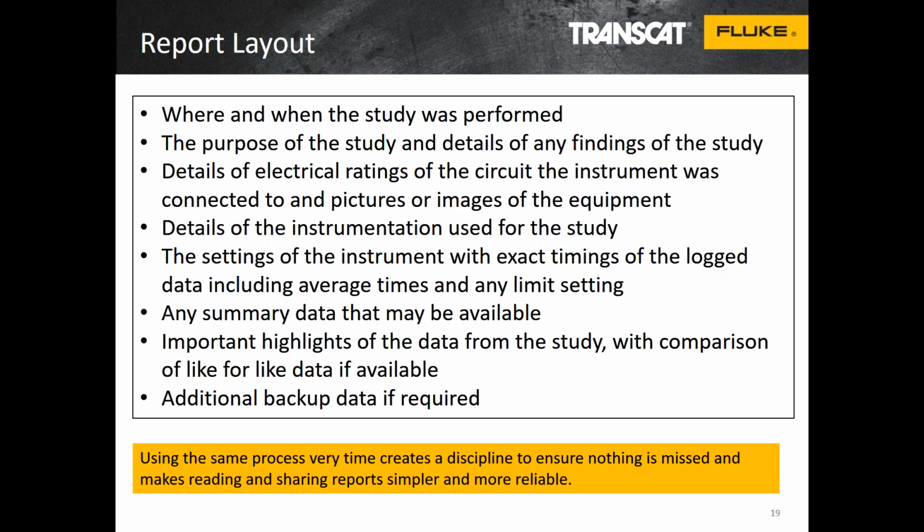Also, I would say this every time, make sure that you choose the right time to make measurements over. We have some products which can measure values every quarter of a second, and we get customers who come to us and say, we've ended up with gigabytes of data because we measured for a quarter of a second for 2 weeks. They end up with a huge amount of data and it becomes difficult to handle. They don't necessarily need quarter-second data for that length of time.